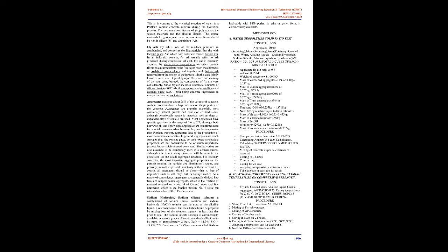The water in a geopolymer mixture, therefore, plays no role in the chemical reaction that takes place; it merely provides workability to the mixture during handling. This is in contrast to the chemical reaction of water in a Portland cement concrete mixture during the hydration process. The two main constituents of geopolymer are the source materials and the alkaline liquids.